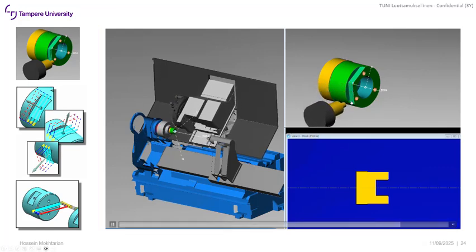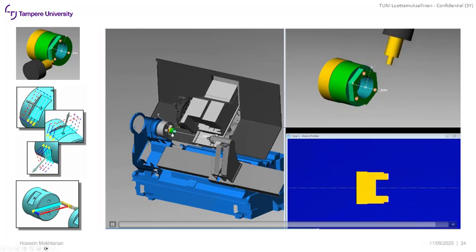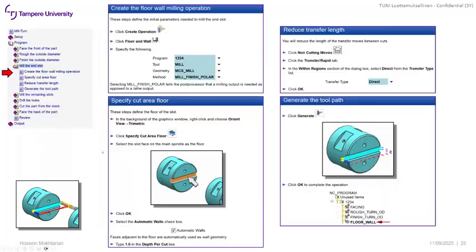However, on this view, it looks like the tool is rotating, but in real life, actually the workpiece is rotating. So this is also something to take into account when we are defining the machining on the slots, either on the faces or on the slots. That is why we are defining the methods as mill polar, and the geometry is on the machine coordinate system mill, which defines that the post processor will generate a milling output as opposed to a lathe or turning output.